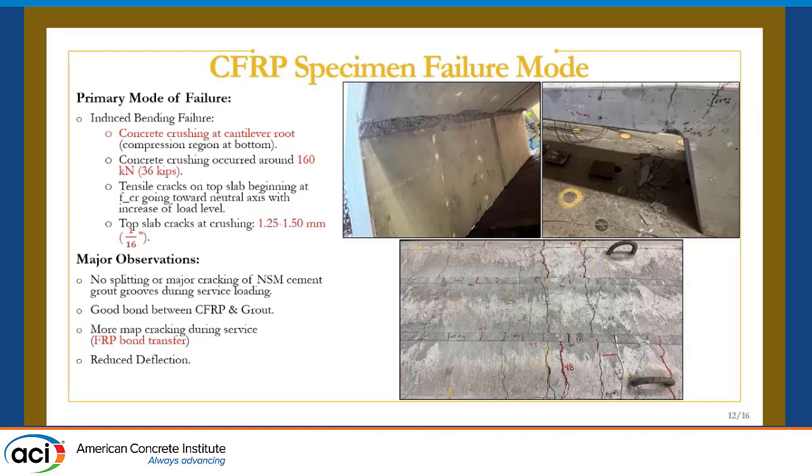groove. So we wanted to use a cement-based grout, very common. CECA 212 is very common in Canada, and I'm pretty sure it's very common in the US. Very cheap cement-based grouts that you can find at Home Depot and are used very commonly. We wanted to save on the cost too, because we know epoxy grouts can maybe give you better parameters for strength, or bond rather. But we went with a cement-based grout for realistic applications.